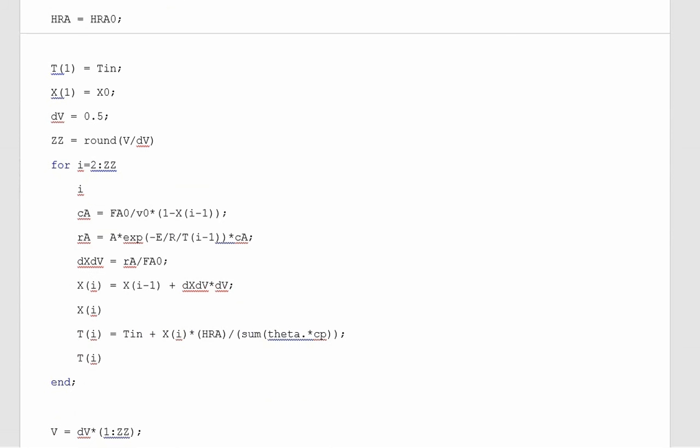So it's saying from the previous point we have values for X and T. So of course when we start this out, we are starting at some initial value here. So at the inlet point, we know a temperature and a conversion. So the temperature at the starting point is the inlet temperature. And then of course the conversion there is 0, right? X naught is 0. And then we run i from 2 onwards. So when we look up i here, i minus 1 refers to the first element. So it looks up T1 and X1.